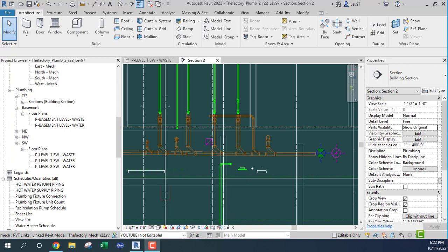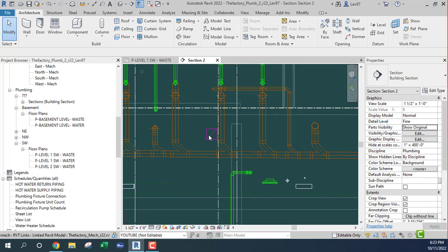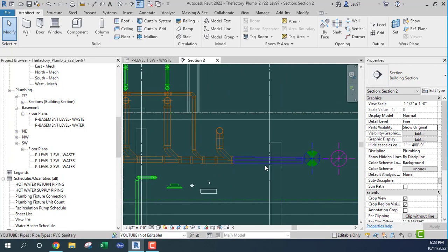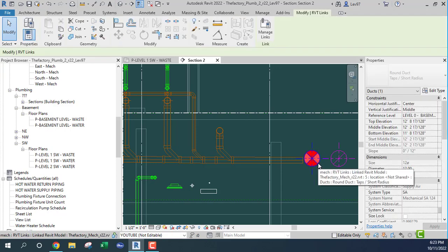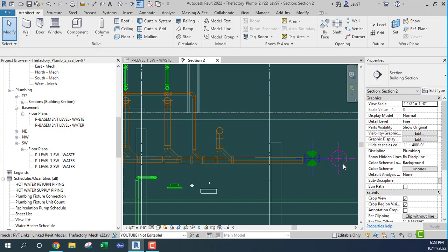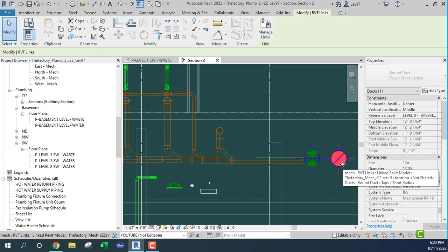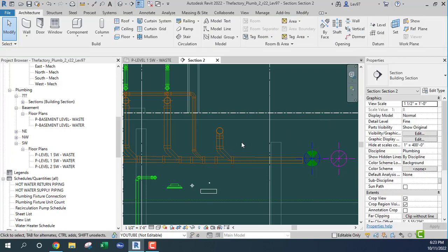Okay, so I think I left off last time coordinating my plumbing drawing with my HVAC, and it looks like even though this problem was solved, when I look out toward the end of my sanitary waste, I have exhaust, and it looks like a return is out here. So that is not going to supply air. I don't think that really matters. Return air.